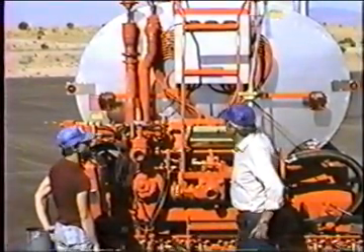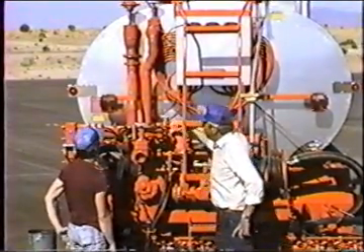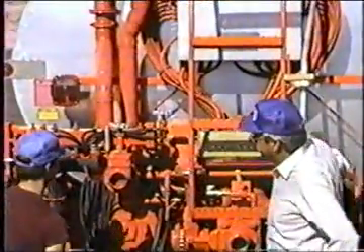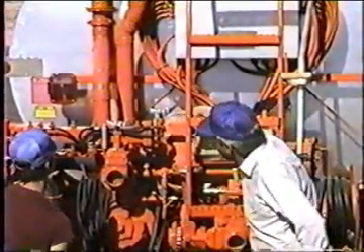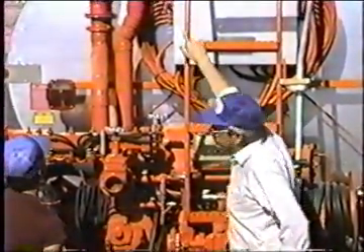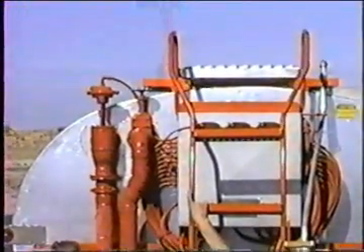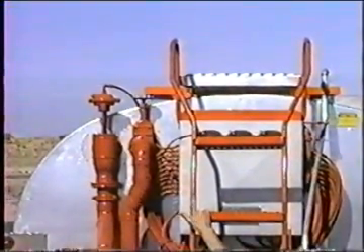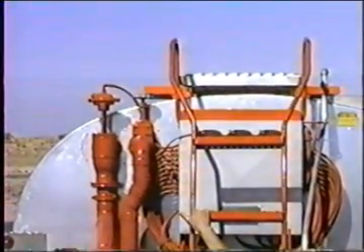Next thing we're going to do is to circulate the spray bar. To do that, we're going to open up the spray bar, open here. Our pump is running in the forward direction. The spray bar valve is open. Get up and close the tank circulate valve. That's got to be closed. Anytime we're not heating, that valve is closed.